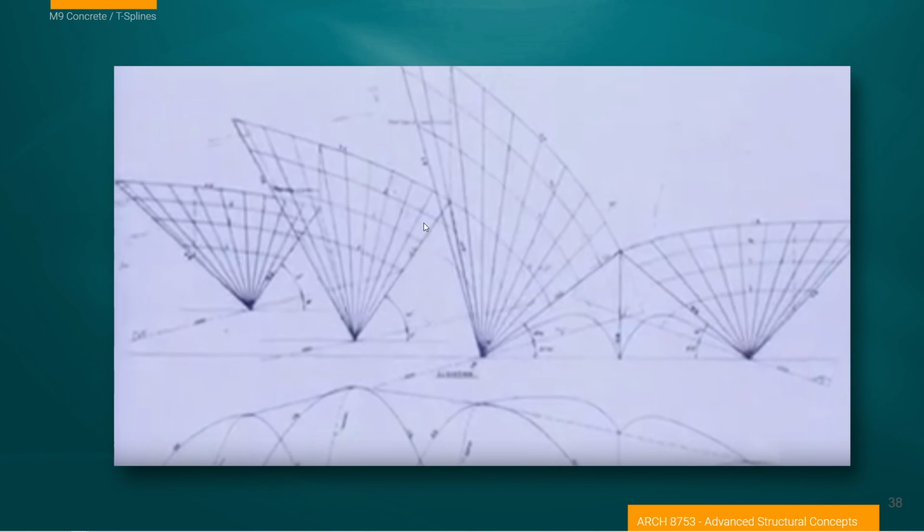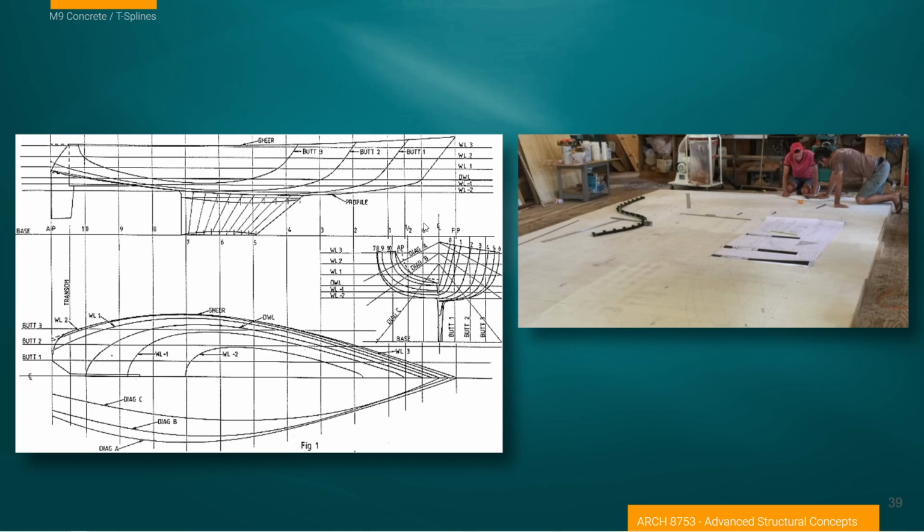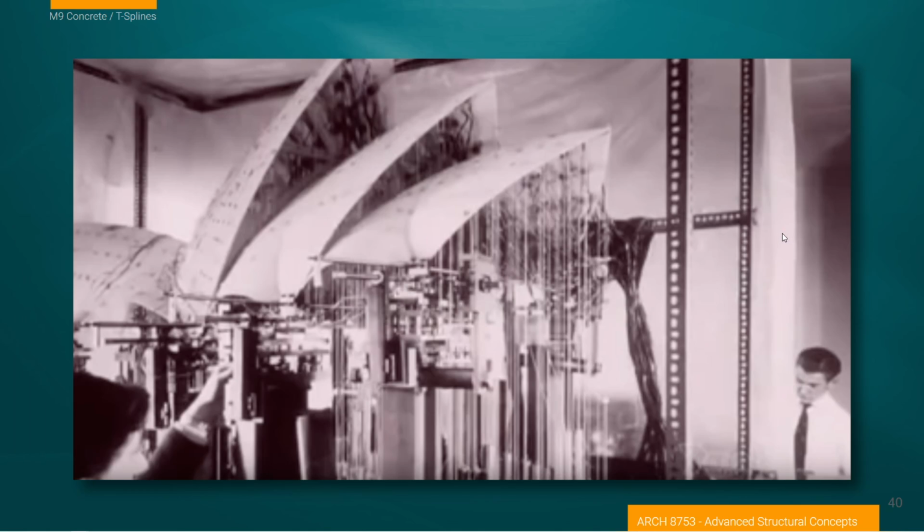I see this image and I think a lot about boat building. I'm sure that people brought the technologies that they knew with hull design. This is a concept called lofting, where you take the geometry and shape at a certain point and you pull it off, and you can generate through two-dimensional drawings three-dimensional curvilinear shape. And this is it now being transferred. In this case, the lofting happens out onto sheets of plywood where actual members are then literally fabricated from that.